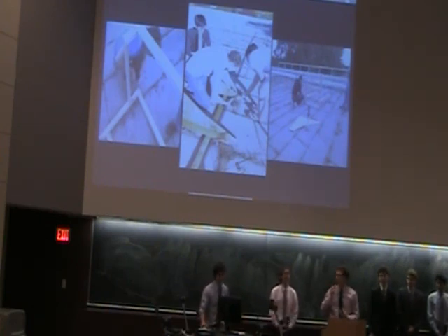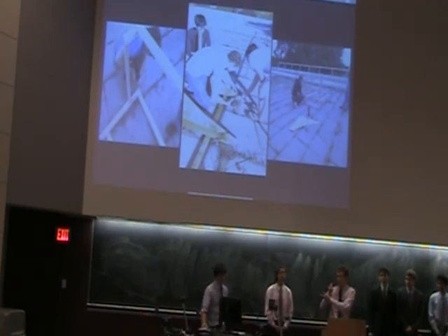I stole it. So here's some more pictures of our construction. The arc length of our actual curves that the reflector is on are close to 1 meter. Our solar cells are only about 3 inches wide. If you think about the fact that all of the sunlight that's reflected on those curves should be reflected back onto our solar cells, that's a concentration ratio of almost 10. Now, we don't think we're going to get concentration quite that high, just because there are inaccuracies in our construction and there are problems with the reflection of the mylar. But if we get anything close to that, we'll have a very, very strong concentration for very cheap. The reflector does not cost much more than the solar cells. At this point, I'm going to turn it over to Ian, who will talk to you about our actual solar cells.